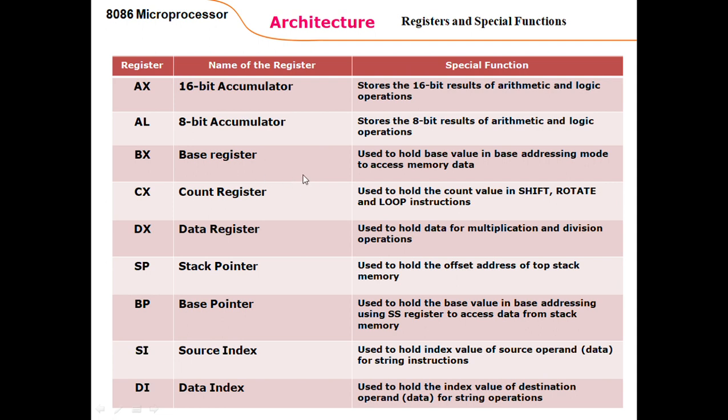BX, the base register, is used to hold the base value in the base addressing mode to access memory data. So the base register is normally used in addressing, even though it's a general purpose register. The same can be used to store the result of arithmetic and logic operations, but there is a special purpose: to provide the addressing or to help in calculating the memory address.